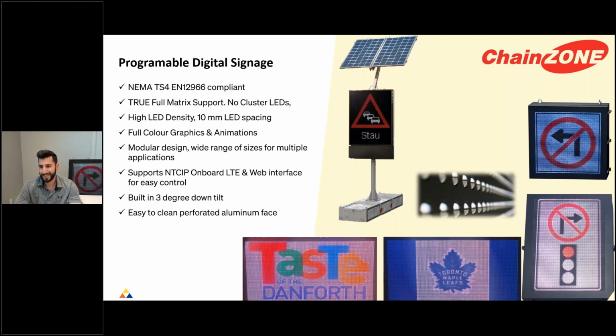Programmable digital signage addresses nearly all the shortcomings of fixed LED signage. And our partner Chain Zone manufactures NEMA TS4 EN12966 compliant digital boards, which are true full matrix LED displays. This means there are no clustered LEDs. Each individual LED on our board can be programmed to generate detailed signs, images, animations, or graphics with, again, no clustering of the LEDs, which is why we can create such detailed graphics in any size, shape, or form.